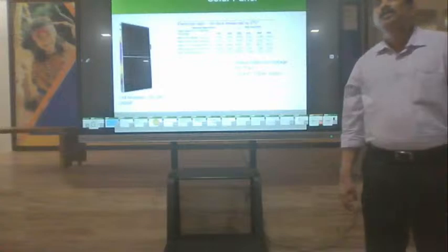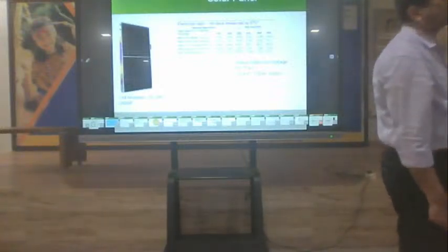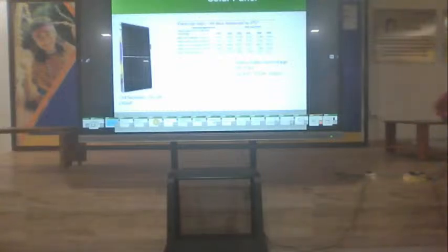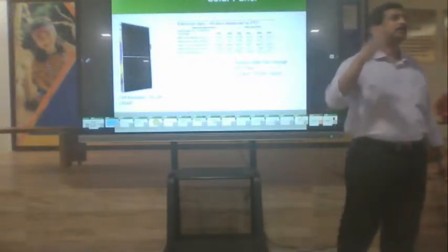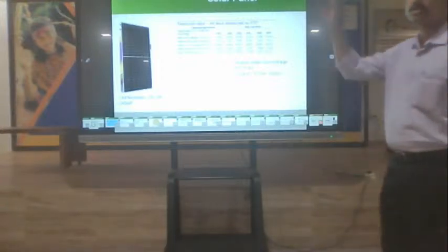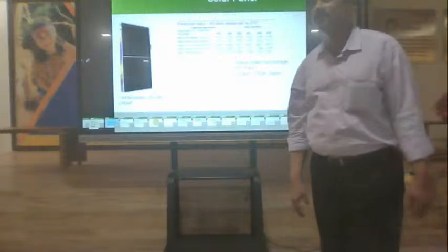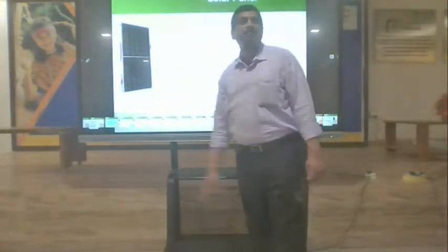Got it? So there are a lot of solar cells of 0.5 to 0.6 volts each, kept in a series-parallel condition to build this wattage. All current adds up in parallel circuits, so there are a lot of parallel circuits. Voltage builds up in series circuits, so a lot of series modules are connected. This is how the solar panel is made.